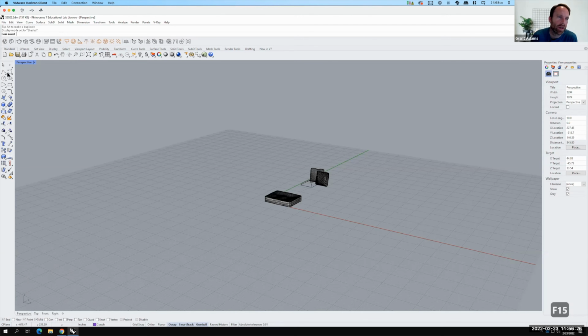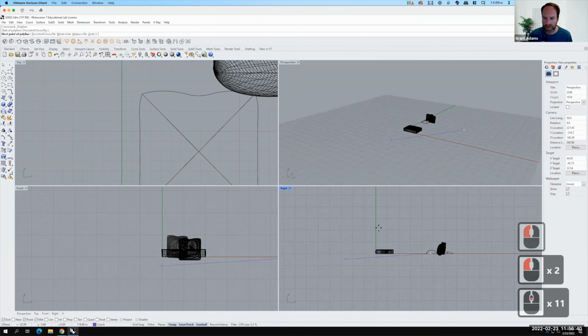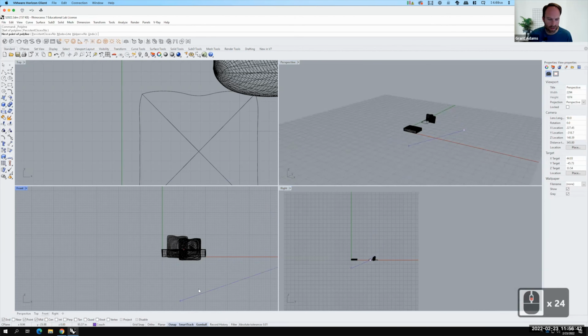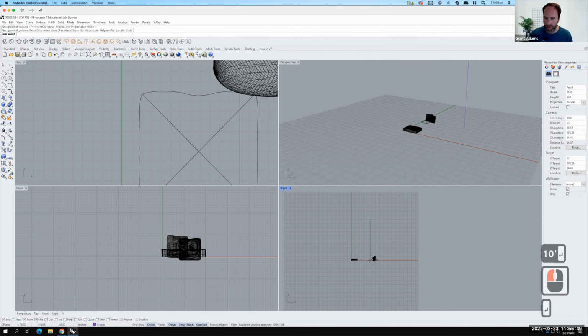A lot of times people want to do tents or fabrics that hang naturally from 2 posts. So if I set up the control, let me start with some polylines. Let's say that I start here and I want to create a vertical line. So I'll move into one of my side views here, and I want to create a vertical line that goes up maybe 10 feet. So there's a vertical line. Then if I go from that same point over, actually, let me snap to the point here. Let's go over.